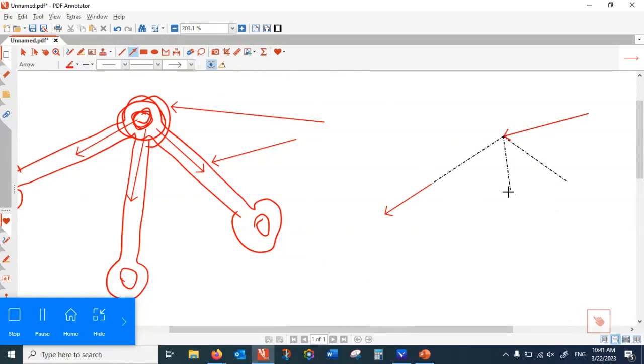If I put the forces like this, these are making my member longer, and therefore I have assumed all these forces are tensile. So this is wrong. Definitely some of these has to be reversed. We only know it after the solution is complete. So by getting a negative number, we realize that something was wrong assumption.